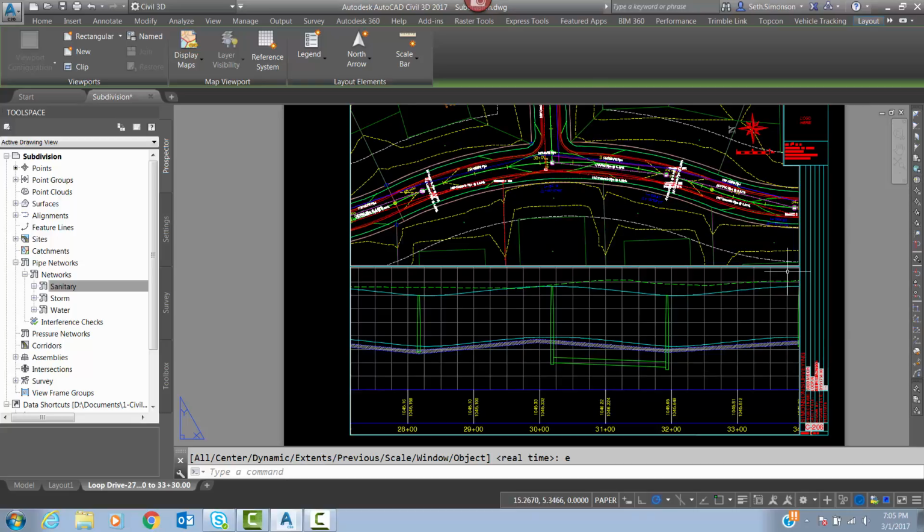After you've focused on this and you've got time, start grading out, making sure your other pipes are at the right slopes and depths and offsets, because besides looking at your printout of this, I will go into your drawing and basically start from the area that you have printed, and probably work another about 3 views or so down the line, just to make sure that you're maintaining your slopes and things are flowing right. I won't go through every single pipe on your site, but I will look a little bit ahead of what you've got here.